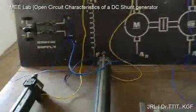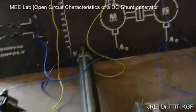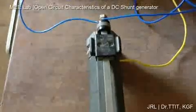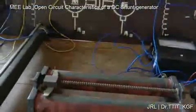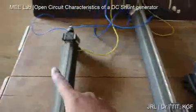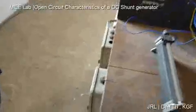Keep all the rheostats in their initial positions. That is, the 50 ohms in cut-in position, the 140 ohms in cut-out position, and the 750 ohms that is connected to the field winding of the generator should be kept in cut-in position. So 750 ohms in cut-in, 50 ohms in cut-in, and 140 ohms in cut-out. Now switch on.